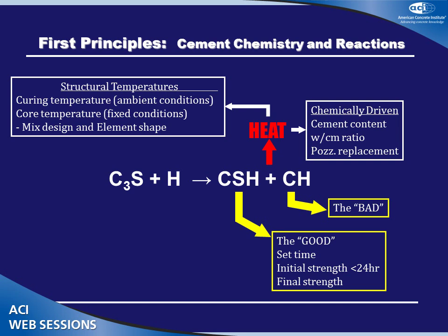My core temperature, huge issue. I get into large, we'll call them discussions. Some people might call them fights. I'll call them animated discussions for the sake of discussion. It's when somebody says, oh, we're concerned about temperature at placement. I said, why? 6 hours later, it's not going to be there. It's core temperature that counts. Well, what's core temperature? Okay, so then we have to start that discussion. The core temperature is largely fixed because it's based on the mix design and the element shape.